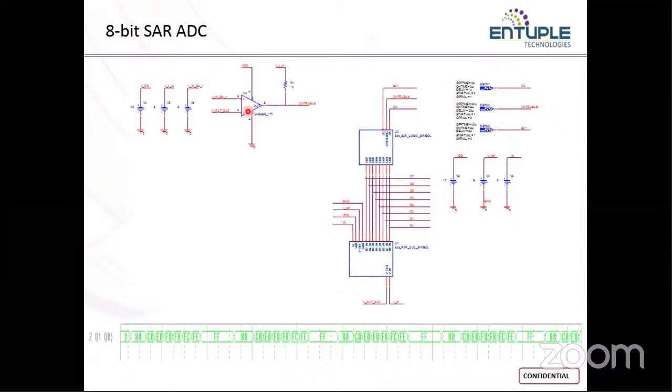Even before you connect all the blocks, it will be better to check individually. First, connect these two blocks and check for the output by giving some sort of stimuli. You know what to expect, right? So you give some stimuli and check for the output. Then connect the comparator. Check the result of the comparator at this stage and at this stage, and then finally check for the output. That is how we have done the circuits.